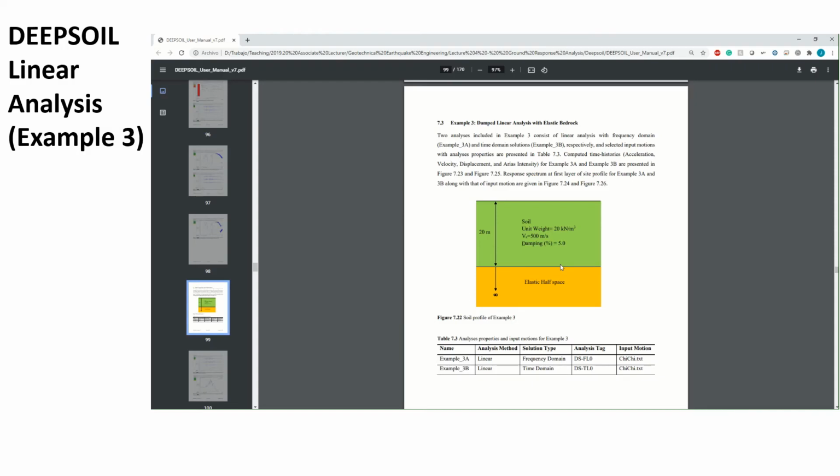If we wanted to go one step forward, it would be with equivalent linear analysis, which I'm going to explain in the next example. The last step could be a non-linear analysis with constitutive models that will require quite a lot of time and understanding from your side. But it is available in DeepSoil, and you could undertake that exercise if you wanted to.